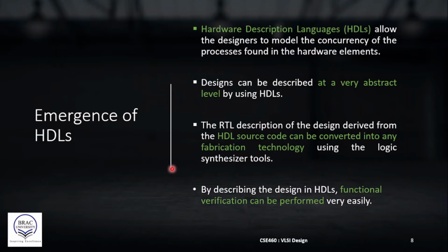HDLs are different from the well-known software programming languages like C, C++, Fortran, etc., in the sense that HDLs can model the parallelism of the actual hardware, whereas the software programming languages are of sequential nature. We use the term RTL description